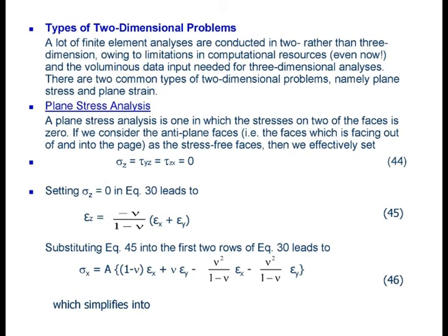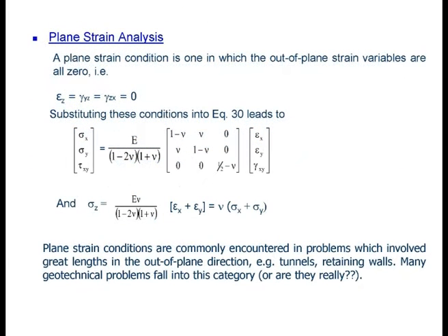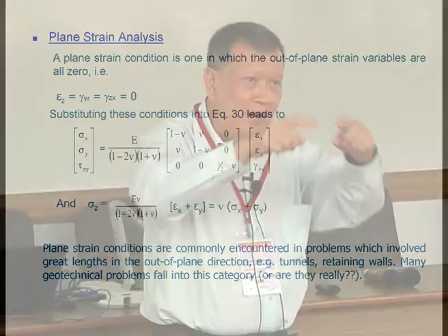So let's move over to the plane strain analysis. Now, what is a plane strain analysis? There is a very strict definition. A plane strain analysis is one where you take a 3D thing, chop it up, take a section view and say this is plane strain. The basic assumption is that in the out-of-plane direction, the thing coming out at you from the computer screen, the normal strain is zero.